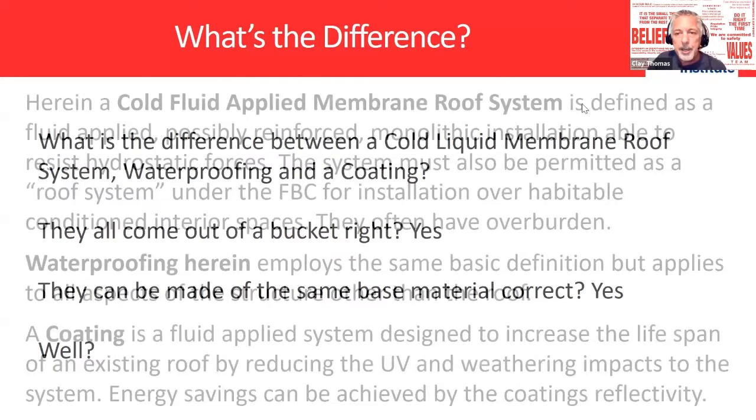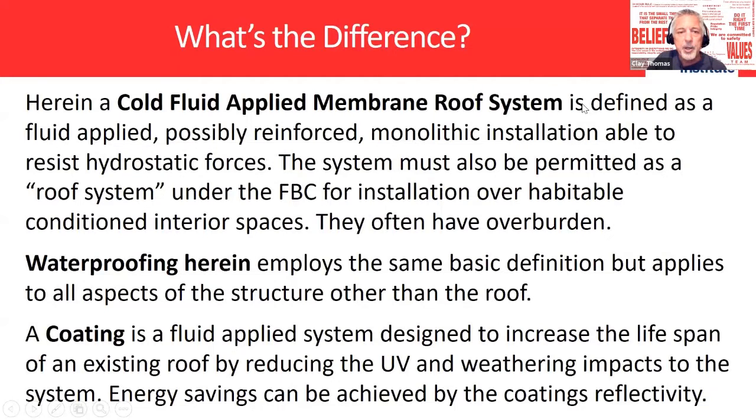Well, what we're talking about today is a fluid applied membrane system, which is defined as fluid applied, and it may have reinforcement, it may not have reinforcement. It depends on what kind of substrate you're going over, and many times your critical areas are reinforced. It may depend on what length warranty you have on that system as to whether or not it has reinforcement in it.